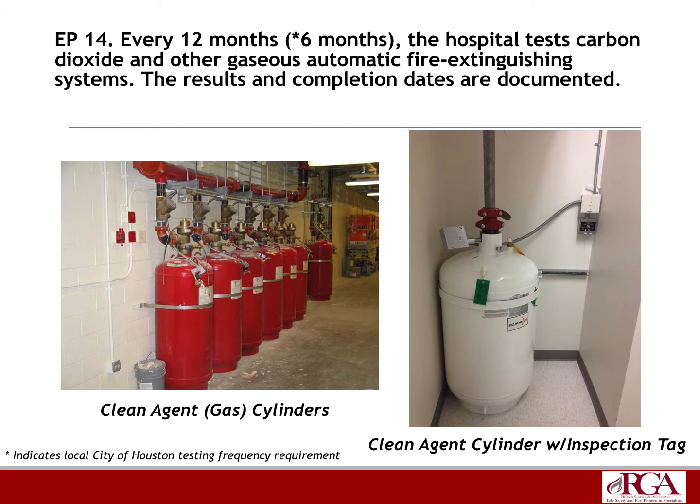EP14, every 12 months, the hospital tests carbon dioxide and other gaseous automatic fire extinguishing systems. The results and completion dates are documented. In asterisks or in parentheses here, you see every 6 months, and that's because here my local AHJ requires every 6 months. So it's actually a good segment to talk about.